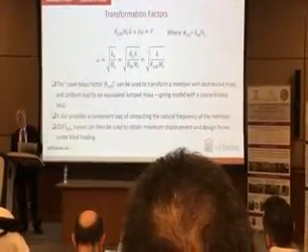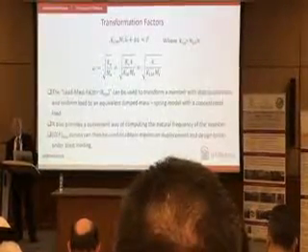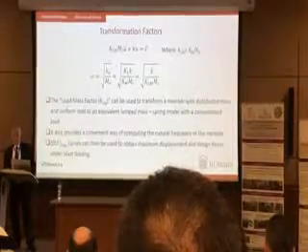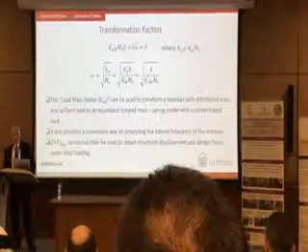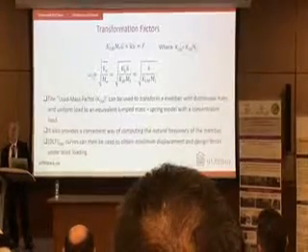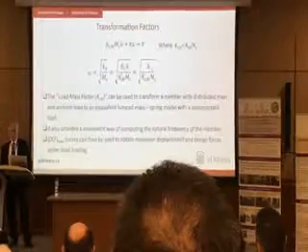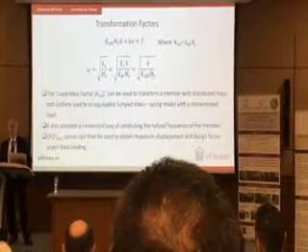So we simplify the problem even further. All I need to know is load mass factor. I apply it to mass only, and I don't need to apply it to stiffness and load. And from that, omega is the frequency of my column or wall, and omega is equal to the square root of stiffness over mass.